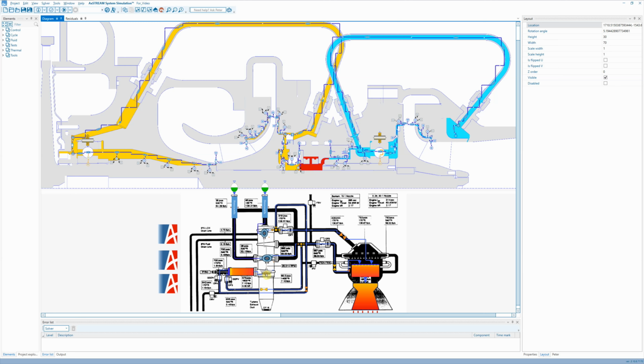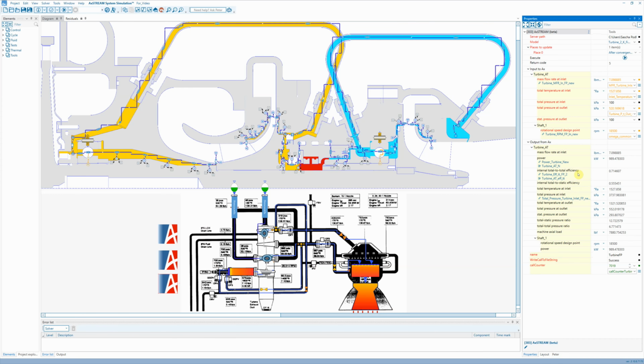So we have the turbine element connected to the turbine geometry, the fuel pump connected to the geometry as well, and so forth. The idea is then that the cycle is being calculated for the different cases, including, for example, different throttling conditions and many more. This will provide new boundary conditions for the 1D, 2D solver, which determines the performance of the turbine and pumps respectively. So we can see here the example efficiency and power output.